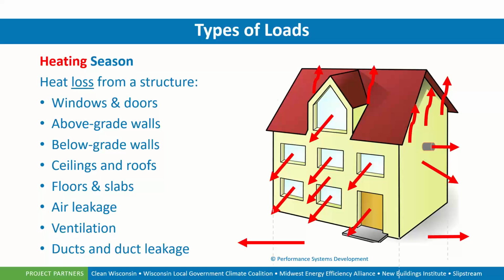So taking into consideration all of these ways that a home can lose heat through the structure, we would want to mitigate those and account for all of this when we do the Manual J. Make sure that we have the proper insulation values in place. Now we also have the proper leakage values assigned. So we have heat loss during the heating season.